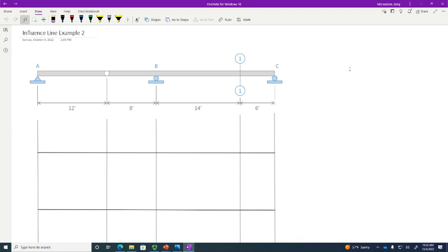So the structure, is it statically determinate, yes or no? What's IE for this structure? 0. Because we've got 1, 2, 3, 4 reactions, 3 equations of equilibrium, 1 equation of condition. Statically determinate.